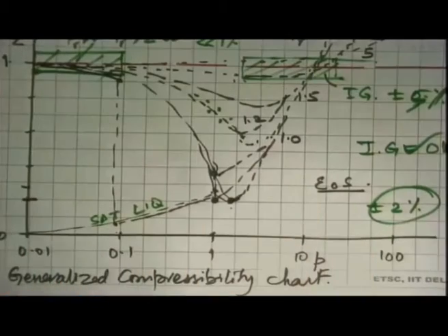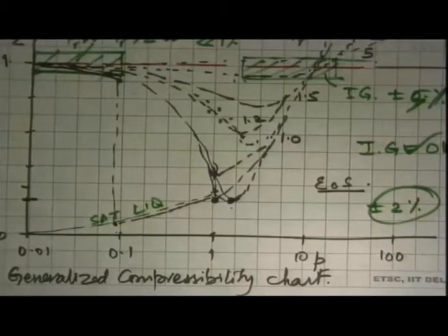The second thing is also that when we write the property charts, it is always nice to move away from absolute values into normalized values, and then you get an equation which has much larger applicability than an equation with properties for that particular substance. So we get a little more versatility in the same equation being used for many substances, and that's where this P_R and T_R come in.